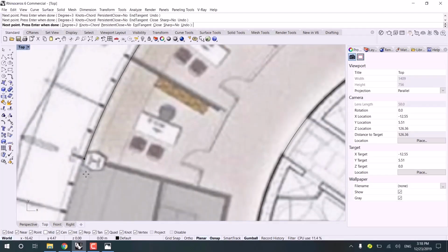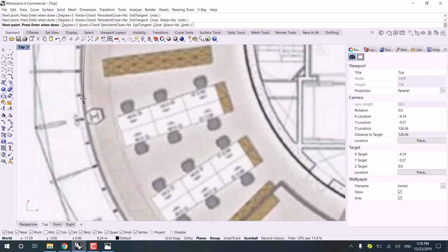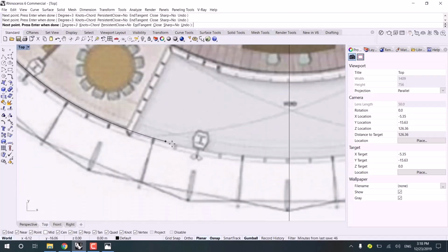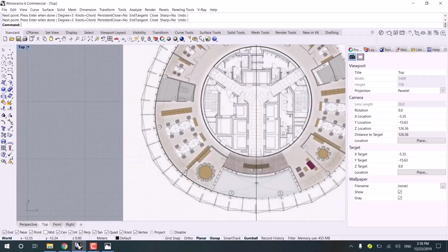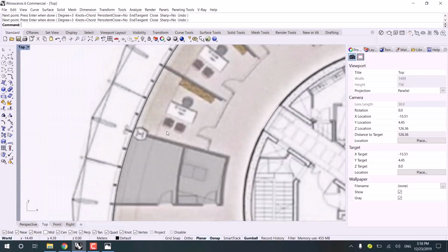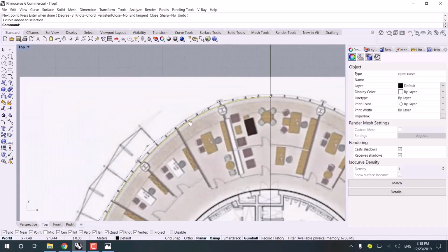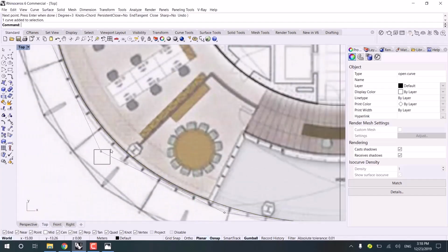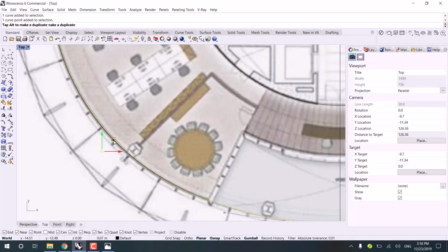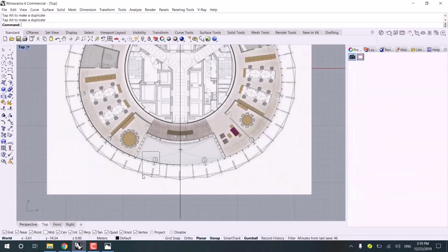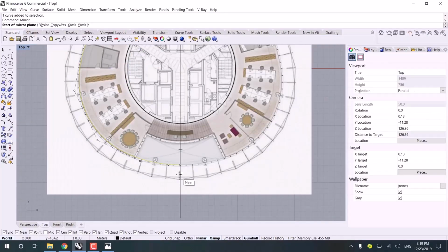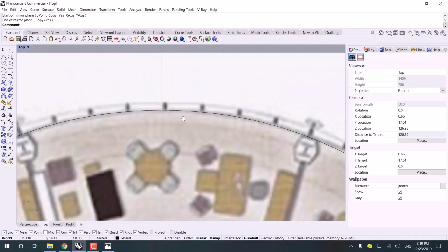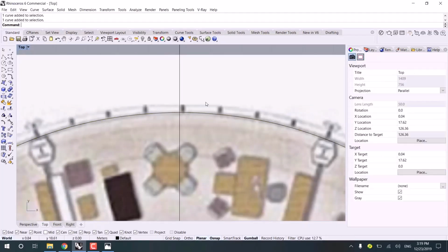Of course, I don't care that much about the accuracy here, because after I'm done with drawing, I can select the control points and do whatever I want on the curve. I mean, I can make the changes later. And next I'm going to apply the mirror command, and I can create the symmetry of my work.